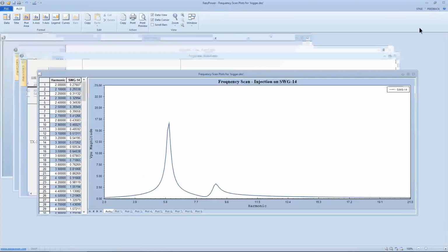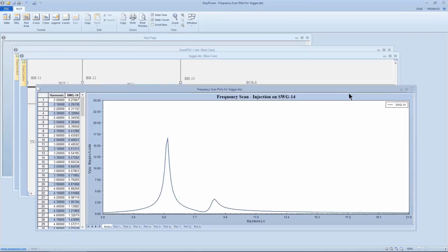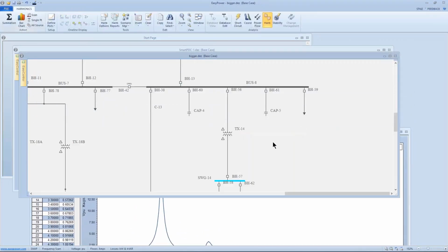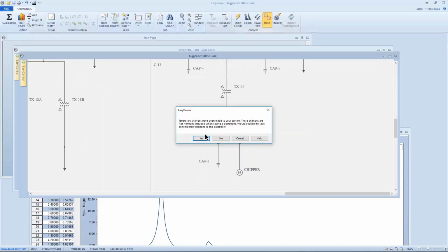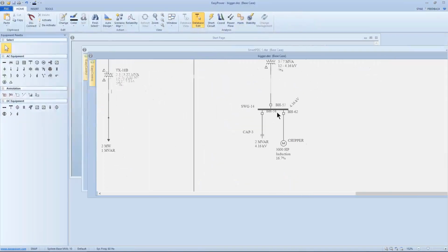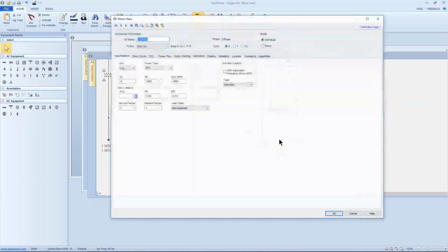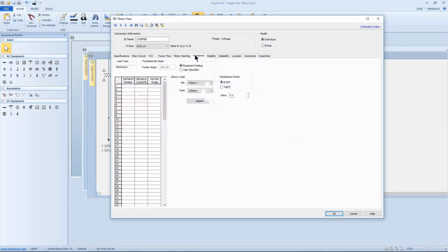Well, when we come back to today, where there's a reason to push towards VFDs, if we want to simulate what that impact would be, we come to our motor controller, make it a VFD controller, and input from the equipment library a typical harmonic distribution or pattern spectrum.